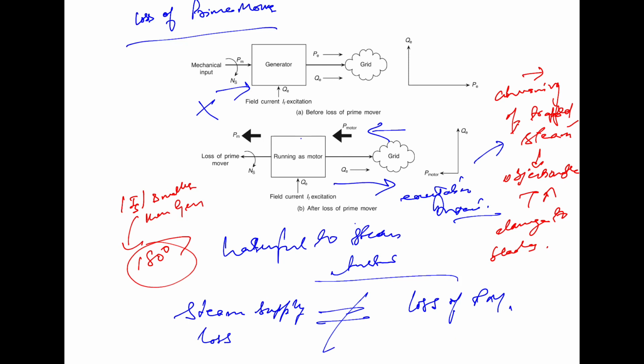However, the magnitude of this reverse current phasor is quite small compared to the forward current, as the generator draws just enough real power to meet the losses and drive the turbine. Hence, the directional relay for detecting the loss of prime mover needs to have a high degree of sensitivity compared to the directional relay used for the overcurrent protection.